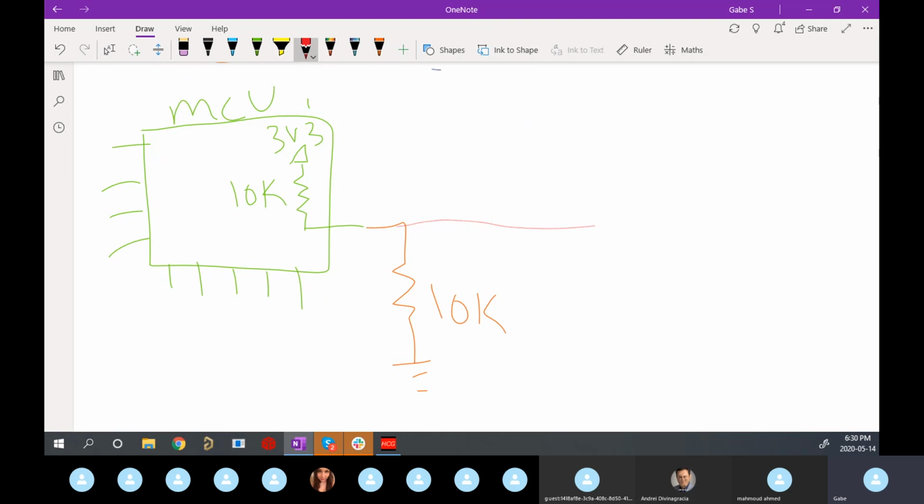Now what you're doing here is demanding two things from your system at the same time: you're pulling it up and pulling it down. You're putting it in a defined state for sure, but the only problem is it's a state that it can never change out of.